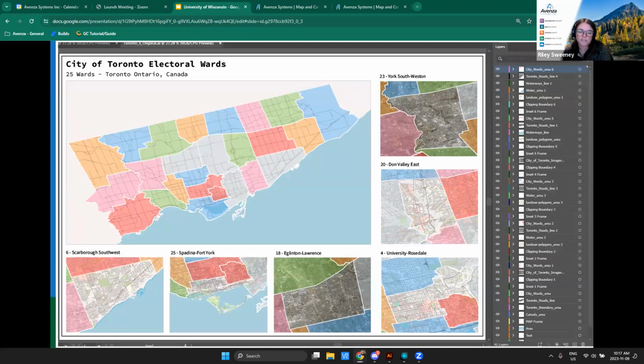I think for users that come from Illustrator experience, the instinct is to work from that layers panel. But when it comes to a spatial document, we have to remember that working with the map views panel and the layers panel simultaneously is the best approach. So that map views panel will show you what area and scale is being represented by a map layer. It also shows you which layers don't hold spatial information, so they won't be affected by changes in projection or scale. And the layers panel is where that drawing order is displayed.